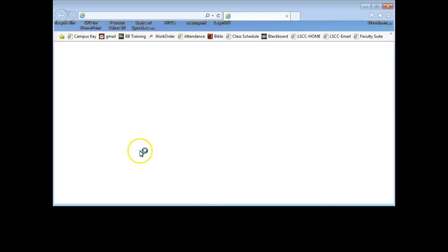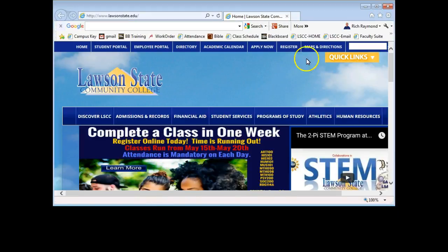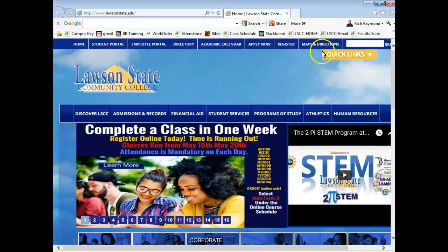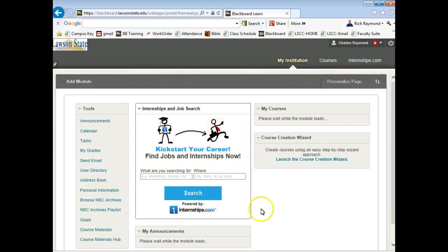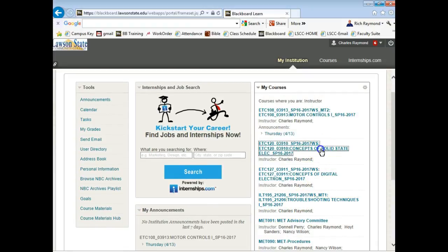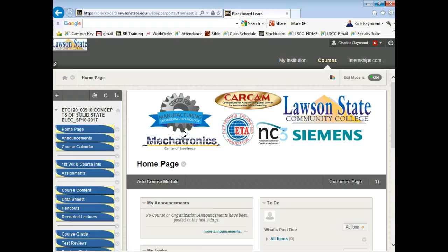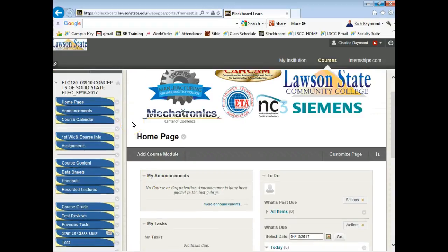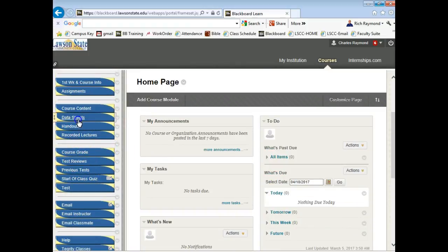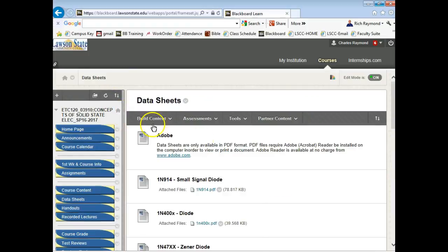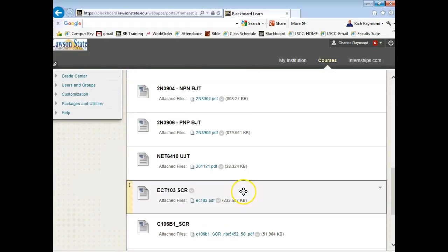So all them pins on there, those 1, 2, 3, 4, 5, 6, that is not the 7-segment display that we're using. So you need to mark those out and then go on the Blackboard. And then put the pinout on there. So you need to develop the pinout for the 7447, which is the one we're working on now, and then later the 74147. So the 7-segment display that we're using should be up here somewhere.